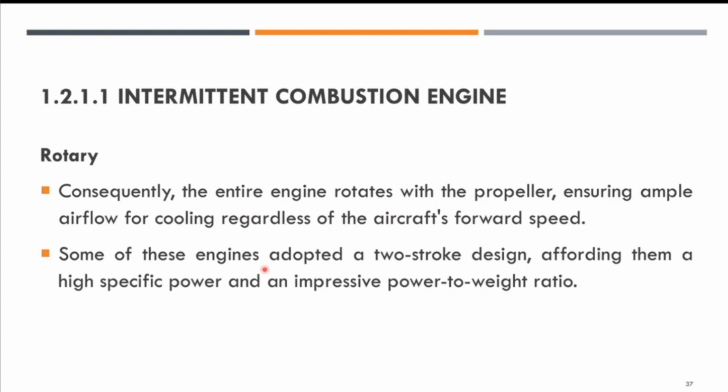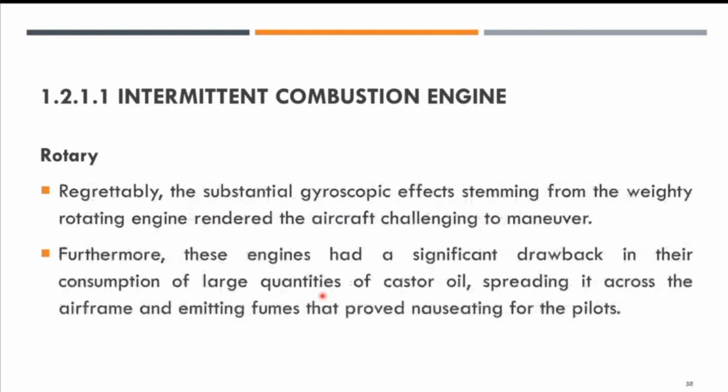And some of these engines adopted a two-stroke design, giving them specific power as well as an impressive power to weight ratio. However, it is regrettably the substantial gyroscopic effect stemming from the weighty rotary engine, it is quite heavy as well, that rendered the aircraft challenging to maneuver. So it is very difficult to maneuver, because for fighter aircraft, it has to be high maneuverability.